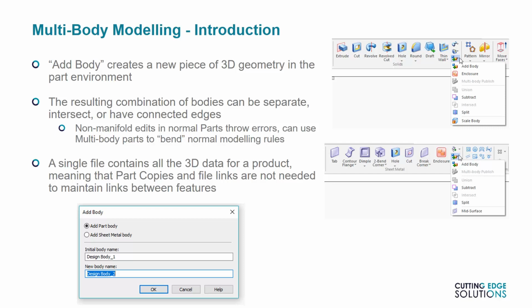The first is that when operating on one design body, the Parasolid modeling kernel has a number of rules that cannot be violated. For example, the non-manifold body rule, which dictates that edits that create solid geometry with infinitely small thickness in any point will fail. The easiest way to show this is with a simple demo.